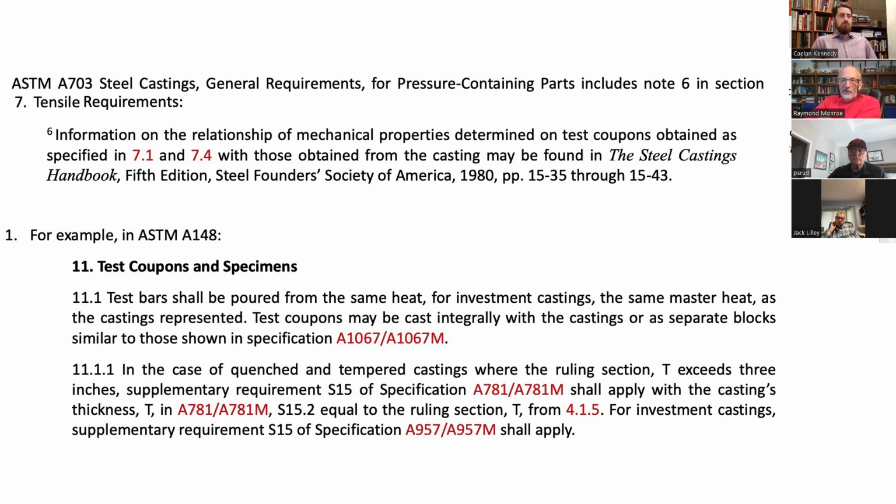Now, customers often think that I should know the thickness just looking at the casting, but that's silly, because there are parts of the casting he doesn't care about, and there's other parts that are critical. And if he doesn't tell me the thickness, I don't know it. So if he doesn't tell me the thickness, this requirement doesn't apply. If he doesn't tell me T, I can do anything I want.